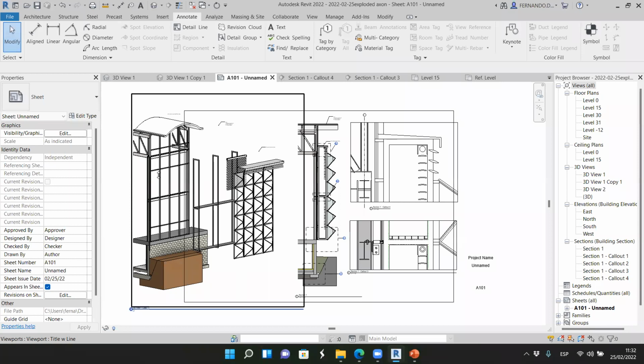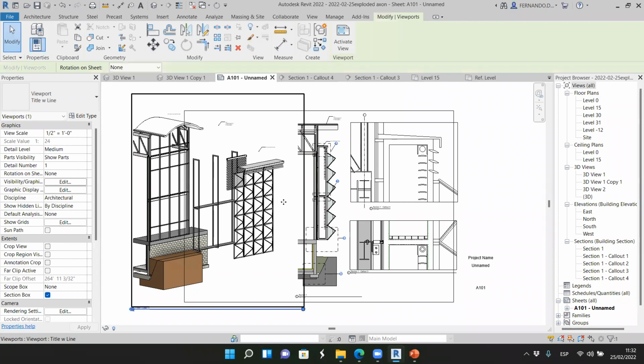It's a storefront. We can do this with Revit easily. Then we need the exterior glazing. It's another curtain wall. We can use exactly the same pattern that we have done in Revit, or we can try something different. We need to connect these two glazing, the interior and the exterior. And that way we have this frame.